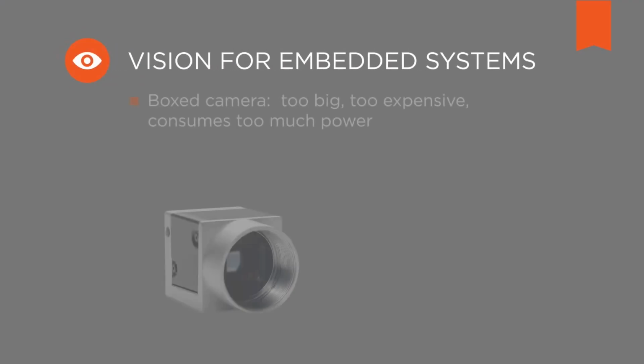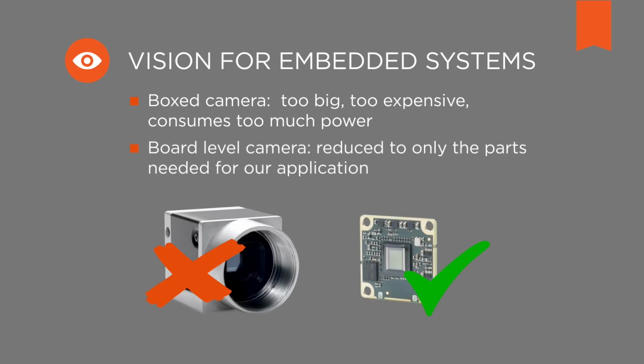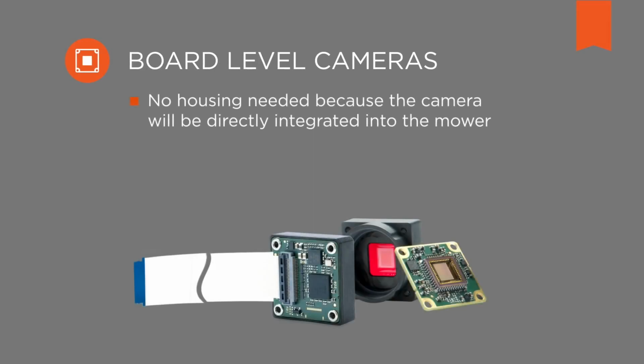How do you integrate vision into your embedded setup? A boxed camera would be too big, too expensive, and would also consume too much power. A good option would be a camera module, a board-level camera. This kind of camera is reduced to only the parts needed for your application. For example, we don't need a housing, because the camera will be directly integrated into the mower. This saves space, power consumption, and most importantly, costs.